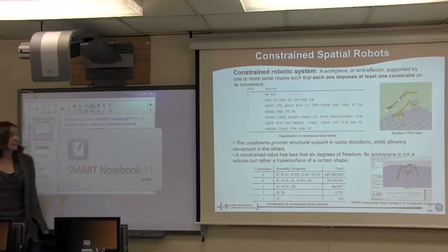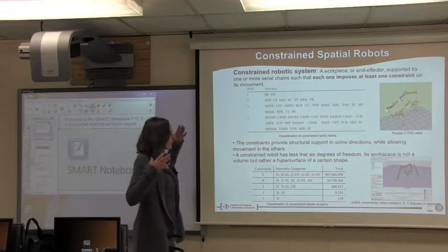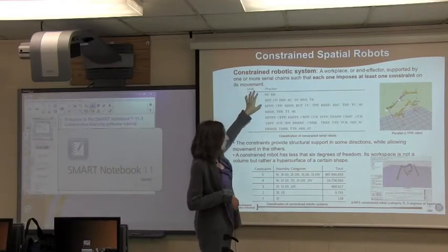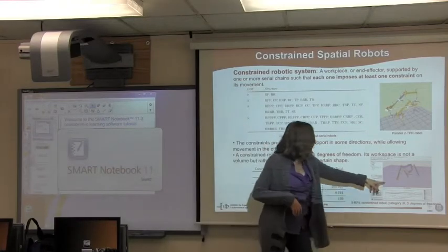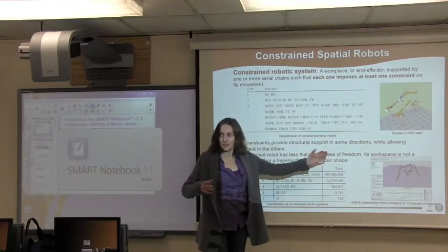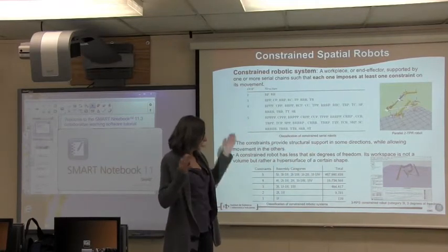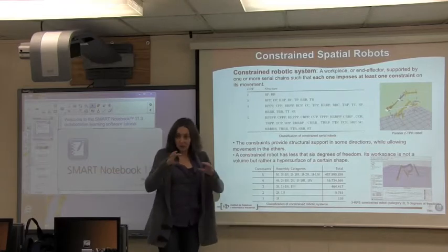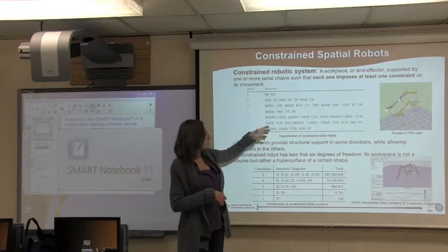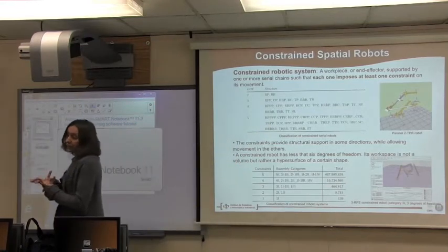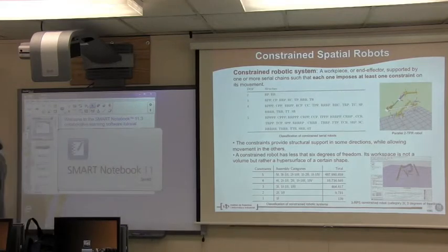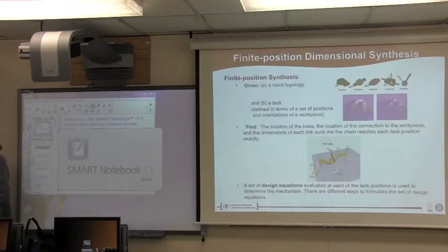And basically, in this one we were trying to illustrate how many different solutions you have. When you have serial chains, you have a few, but when you start assembling them and creating parallel robots, these are all the possible combinations of basic joints. So you have hundreds of thousands of possible structures you can use to perform these motions, just starting with these simple revolute, prismatic, cylindrical, spherical joints. So it's just the number of possible structures, topologies, you can use.